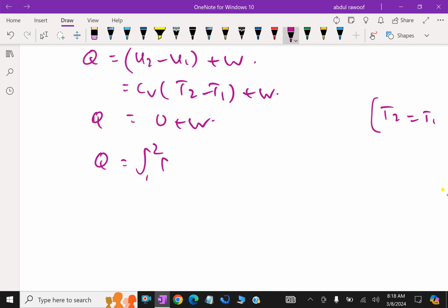Here, we can consider that constant C can be written as either P1 V1 or P2 V2. Now we know that in a constant temperature process P1 V1 equals P2 V2, which equals constant C. Therefore, W equals P1 V1 log base e V2 by V1 per unit mass of the substance.